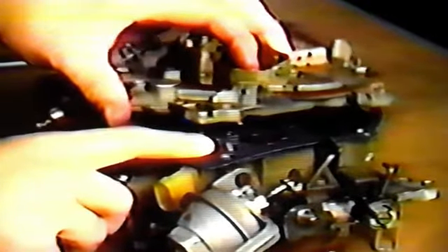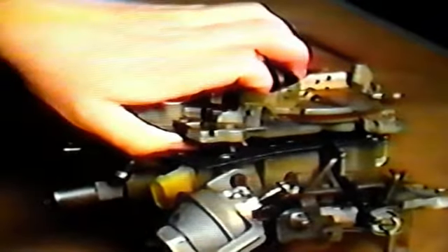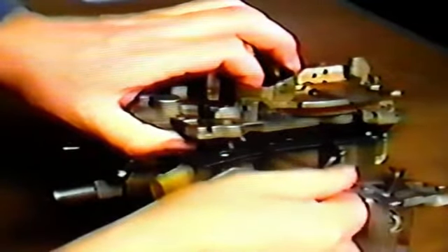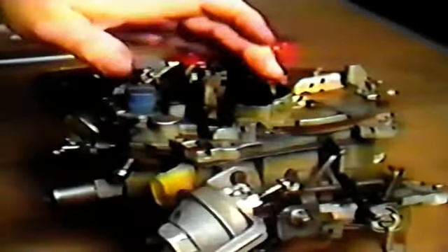This is also the stage where you'll see how removing the throttle position sensor pin earlier can make reassembly easier. The first thing to do is line up the MCS connection and accelerator and hold them in place with your finger. Then take a small straight edge and hold the TPS pin up out of the way and set the top down on the base. When the straight edge is removed, the pin should drop naturally right in place. Only then can you put back all the screws.